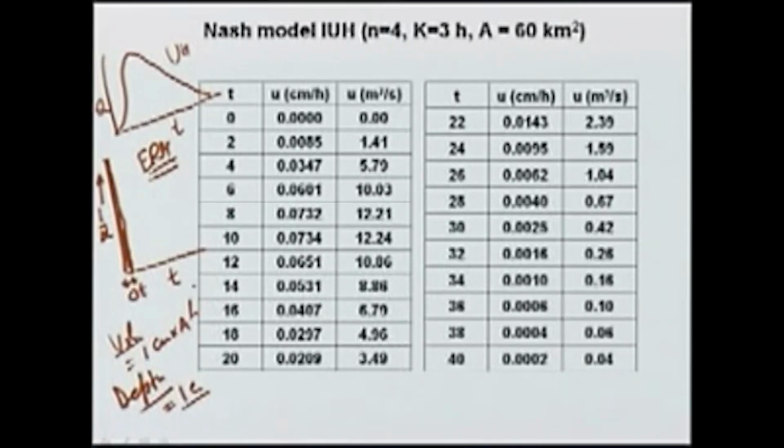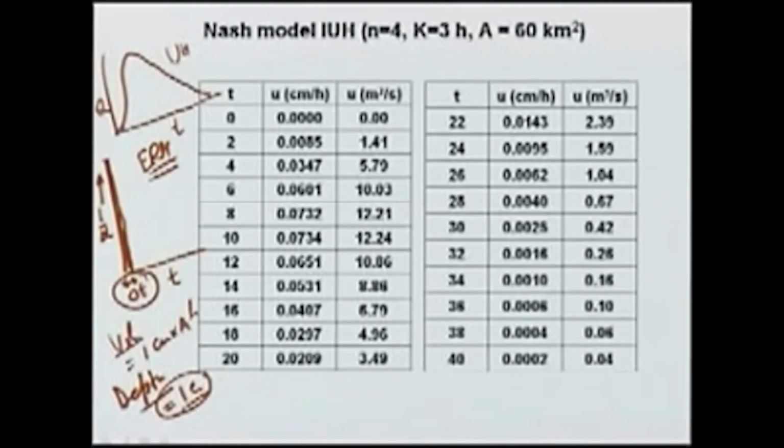but it occurs at almost 0 times. So, as the limit delta t tends to 0, it becomes instantaneous rainfall of very large intensity, very small duration in such a way that the depth is 1 centimeter. In other words, the entire 1 centimeter of rainfall occurs instantaneously at the catchment, and because of that it causes a runoff like this. We have seen that Nash model is one of the models which is used for instantaneous unit graph calculation.